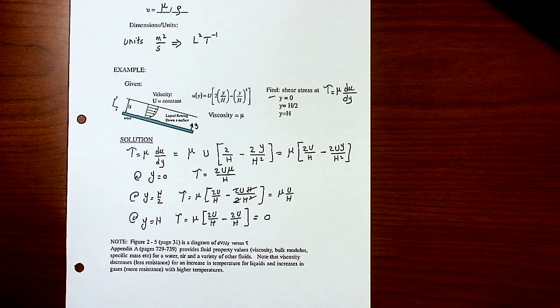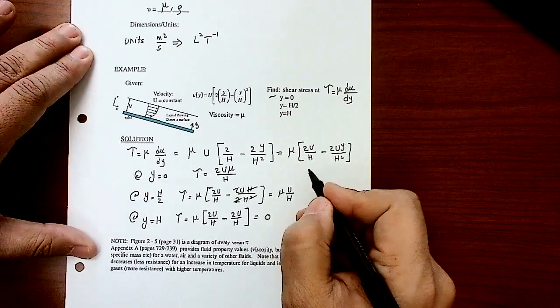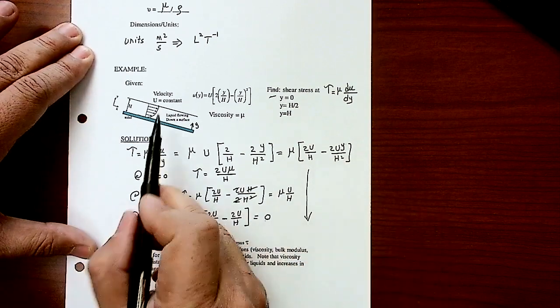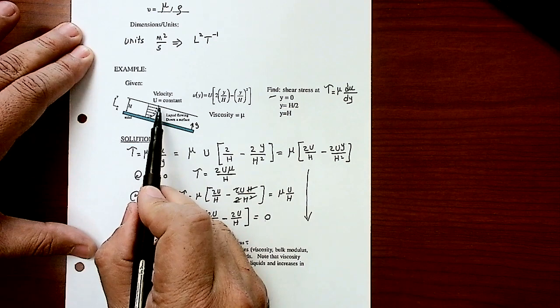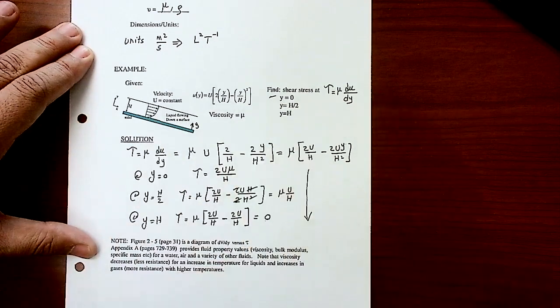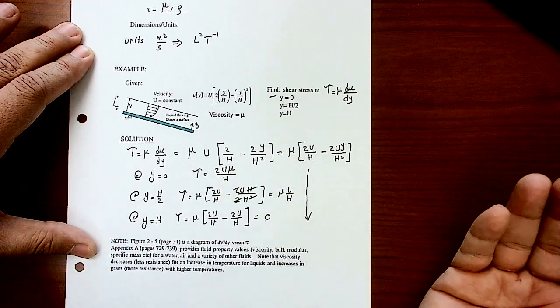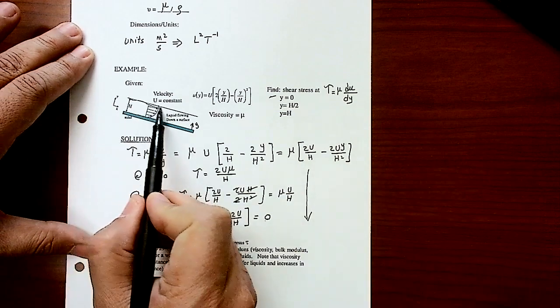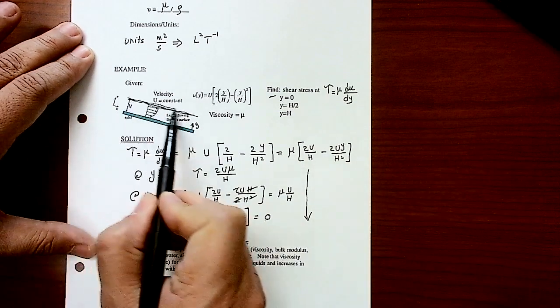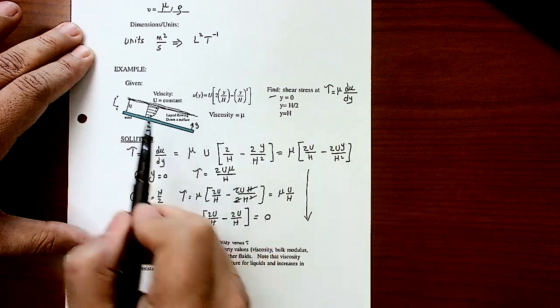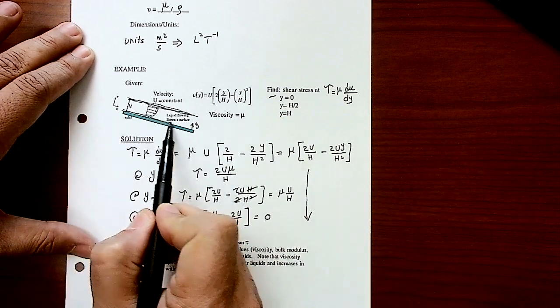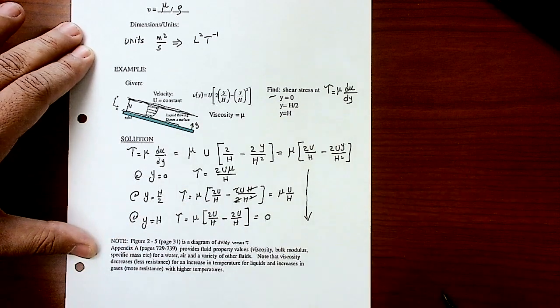Shear stress. Why is the shear stress decreasing this way? It's almost 0 here, because you don't really need that much force, which can be translated to a shear stress, to deform the fluid. It's free. The layer of the fluid here is not affected by anything, right? But the layer of the fluid in contact with the solid has a resistance to flow. It needs higher force to pull that layer and shear it and deform it, right? Because it's attached to the wall because of the no-slip condition.